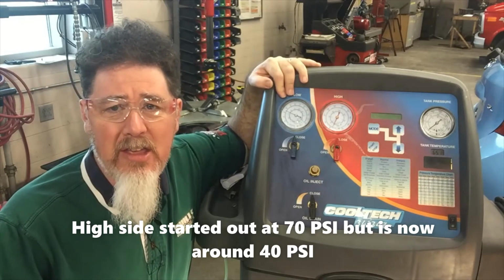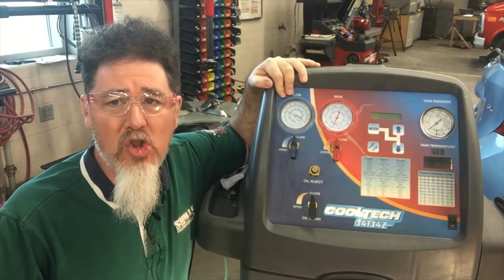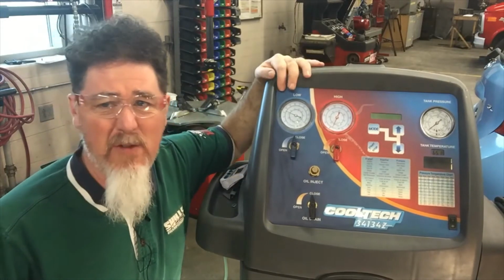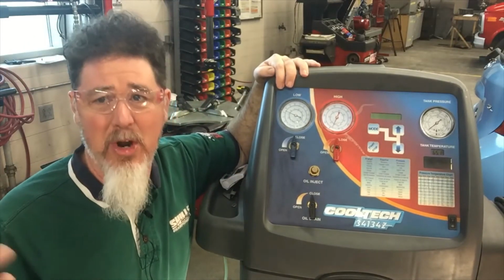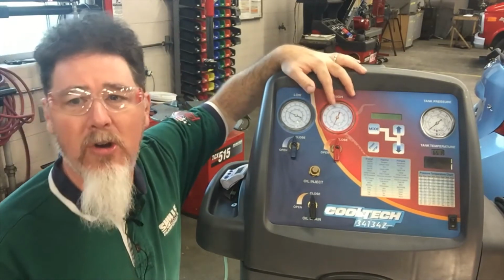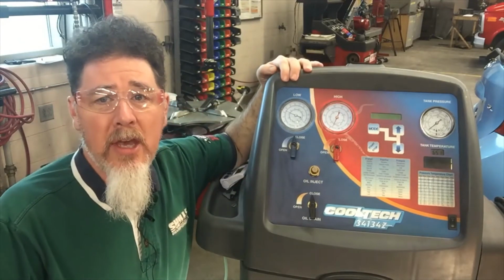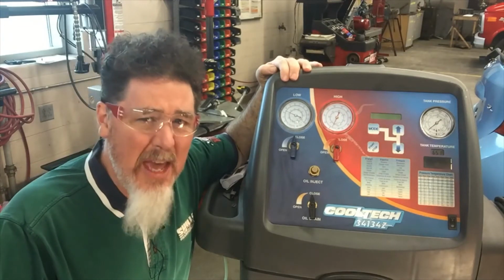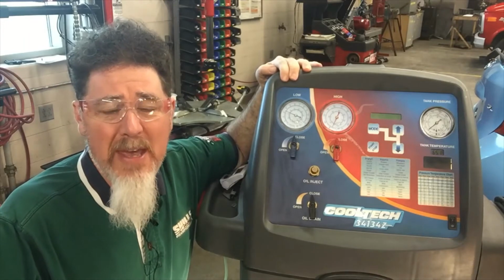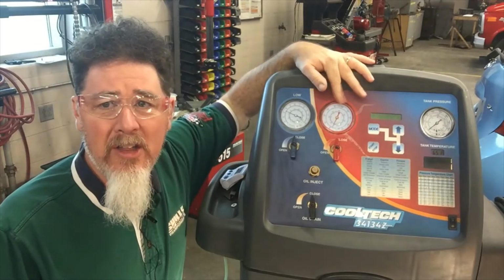If you take a look at this, it is a normal charge system, so the vehicle is fully charged. Since the restriction is before the high side service port, the high side and the low side service port are reading very similar, and obviously the high side is very low. If you tried to do your normal equalization test, or tried to recover on just one port, the results are going to be inconclusive. It's not going to find the restriction because the restriction is before the high side service port.